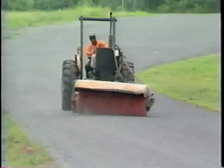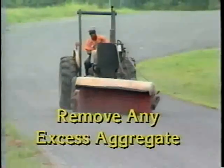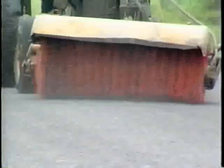Broom the surface lightly to remove any excess aggregate. This is the 7th step in the chip seal procedure. If necessary, this is done after a good bond has been formed between the asphalt and the aggregate. The term lightly is emphasized because excess pressure with a broom could loosen the aggregate.